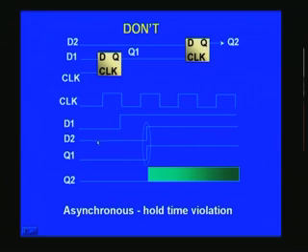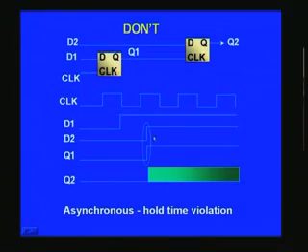So actually these are all the steady state of the previous clock. Normally this will not pose any problem, and only here, that means it already satisfies the setup time, and what is going to be violated is the actual hold time. When the clock rises, the data is not stable. As per the hold time, this data will have to be stable for at least a TH time. Beyond that, naturally this is violated, and you have no control over that, so this has to be eliminated from your design.